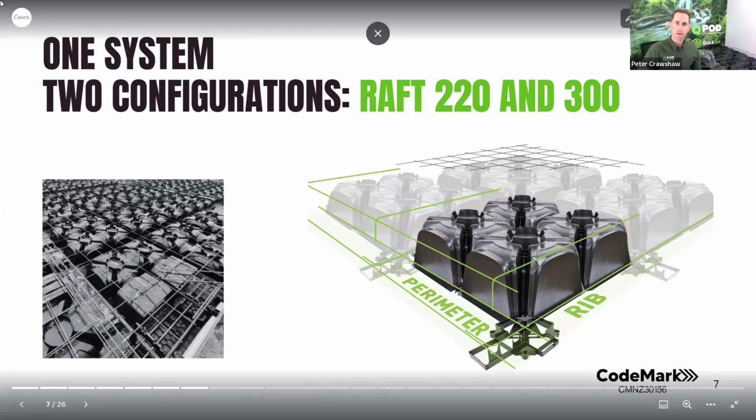Yes. So the R value calculator has the QPOD R values, and the polystyrene being a dense product with a dense wall, and QPOD being a hollow thin wall product, there is a difference there, and it is erring on the advantage of polystyrene in the insulation factor. So on a typical site with no insulation, a QPOD site might get say 1.3 R value, and a polystyrene might get 1.35. The difference being about 0.05 between the two.